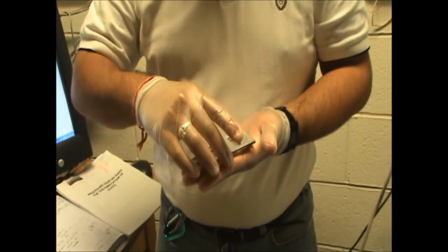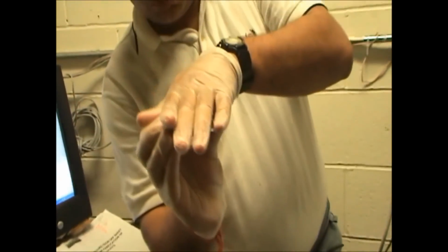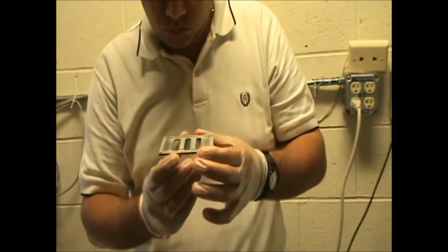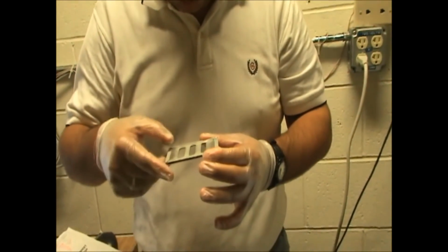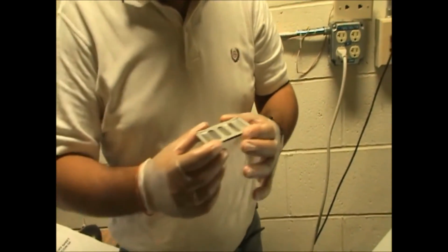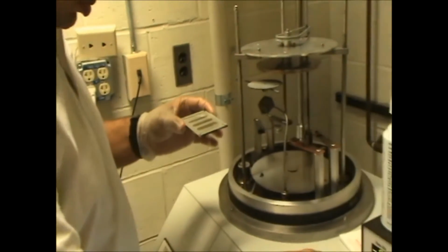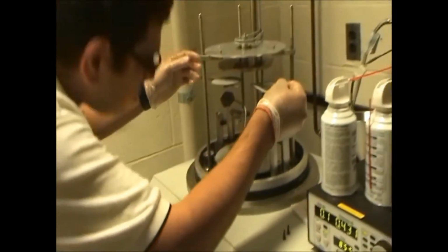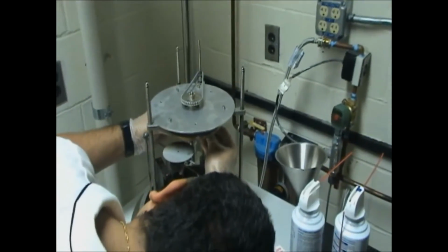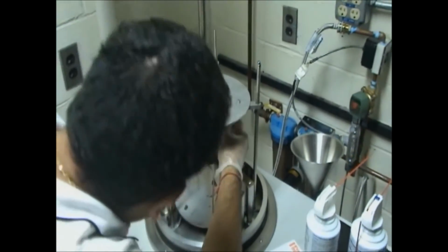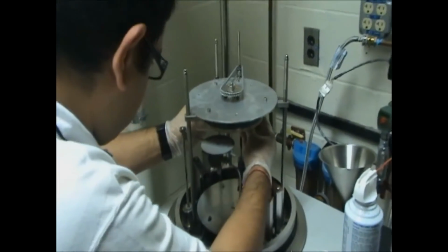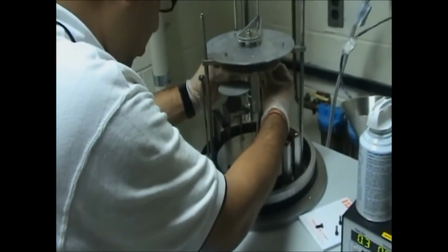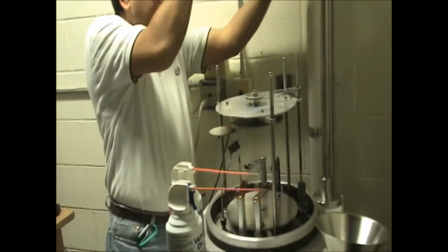The organic layers are deposited by evaporation. First, a shadow mask is put on the slide to make sure that the organic layers are deposited only in the center and that the metal is still available on the edges. Then, the slide is loaded into the thermal evaporator. The material to be evaporated is loaded into little crucibles in the evaporator.